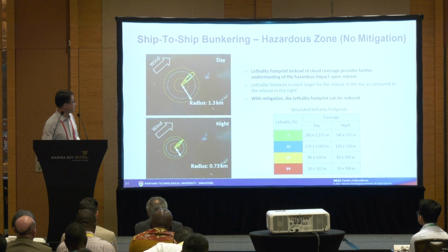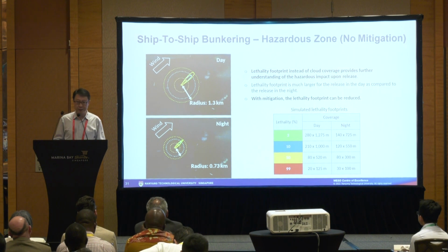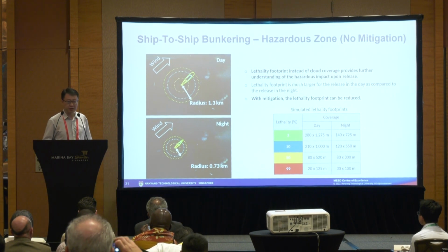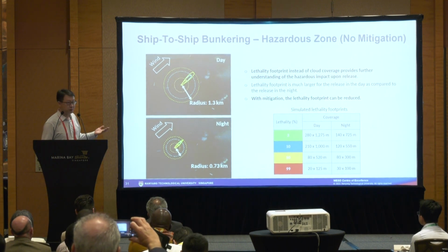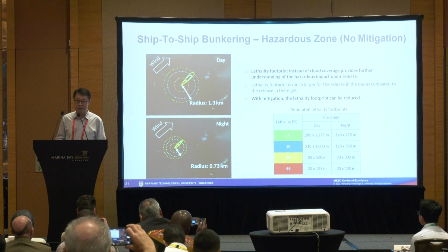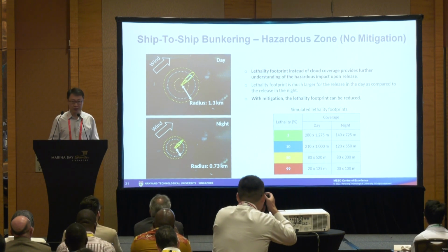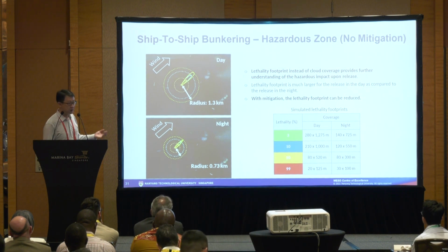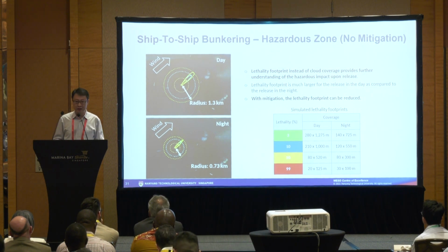So based on this, we can generate a lethality footprint in Singapore. So we are using Singapore weather and environmental conditions. In this case, we are using a lethality footprint, which combines the ammonia concentration and exposure time. So you have a rough idea, at such a big scale release, what kind of safety zone you require.